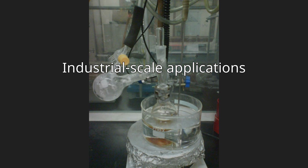Vacuum distillation columns, as depicted in figures 2 and 3, typically used in oil refineries, have diameters ranging up to about 14 meters (46 feet), heights ranging up to about 50 meters (164 feet), and feed rates ranging up to about 25,400 cubic meters per day (160,000 barrels per day).